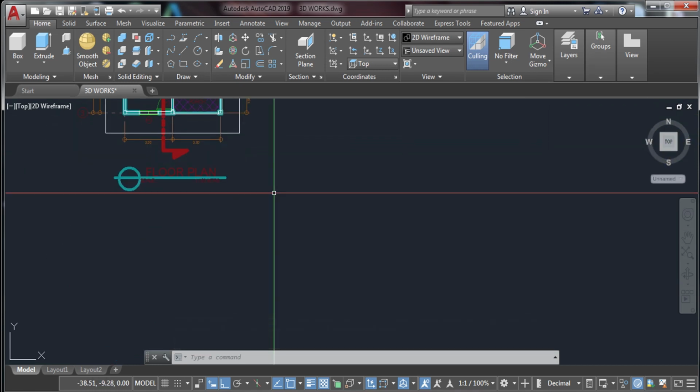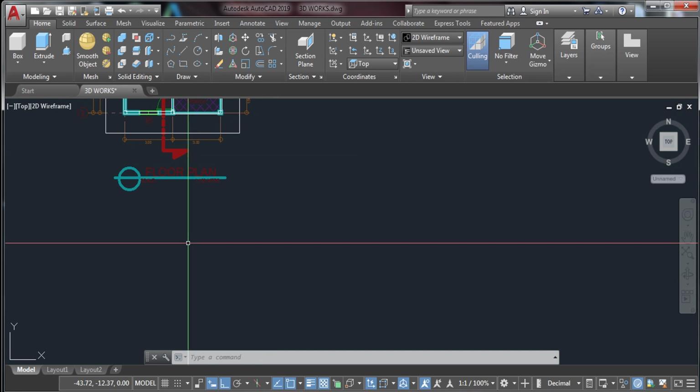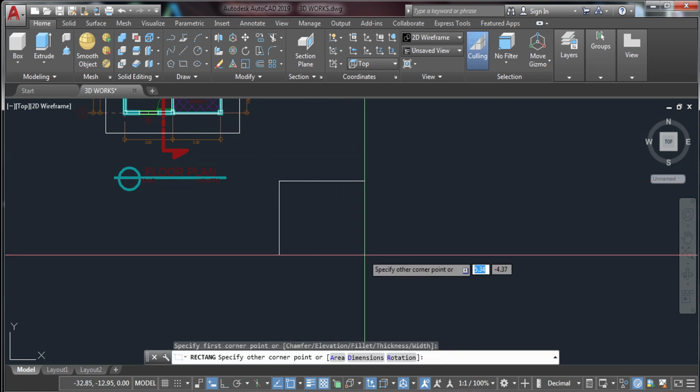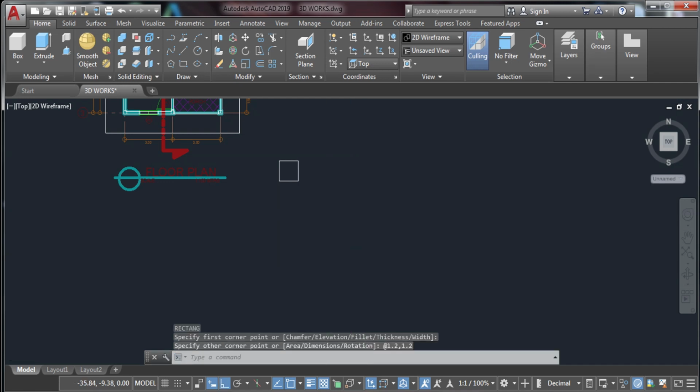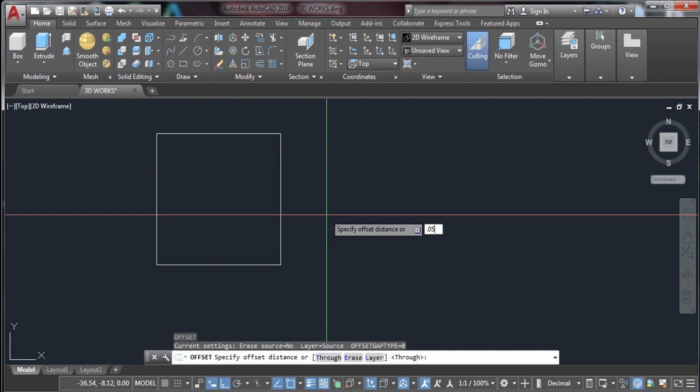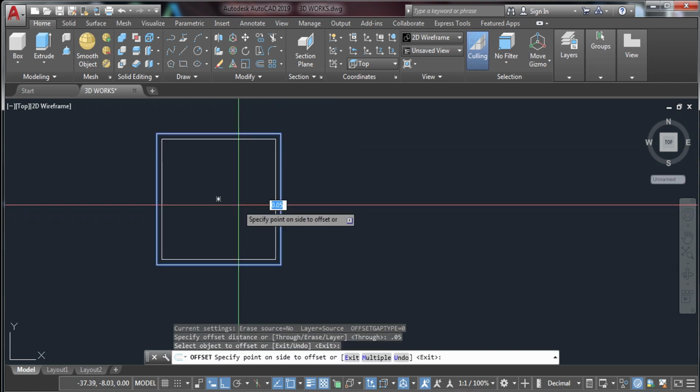There are sometimes you are going to do what we call jealousy window, awning window, nakadepende po yung style ninyo. So, ako, I'm going to draw now a sample of what we call sliding window. So, what should I do? I'm going to type 1.2, tab 1.2 in the most easiest way. And then, I'm going to offset this one by 0.05 and then going inside.